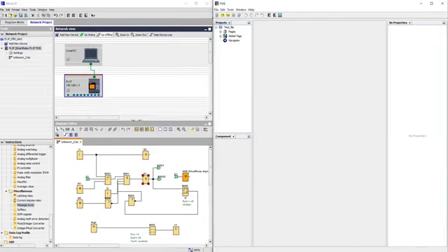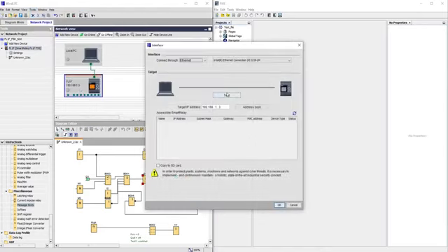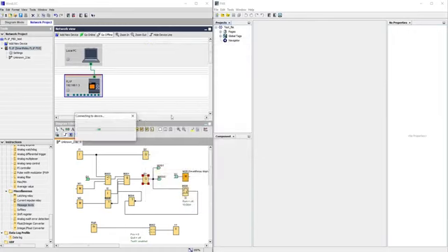So first I'll transfer from the FL1F's backup tools, transfer PC to Smart Relay. Just check whether Ethernet is connected and the IP address is as per the Smart Relay. My Smart Relay's IP address is 192.168.1.3. Click on text. Yes.